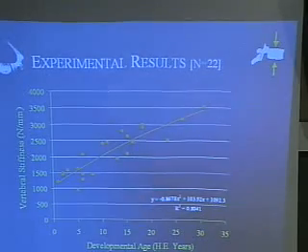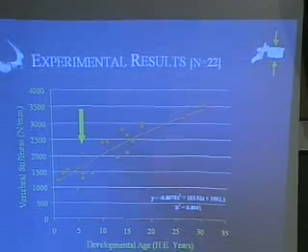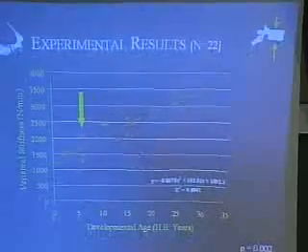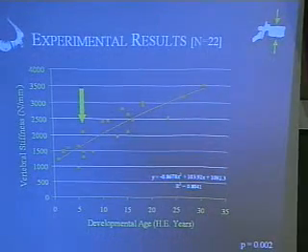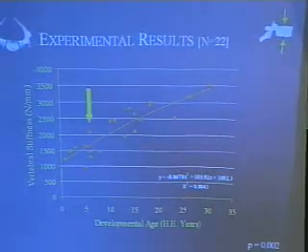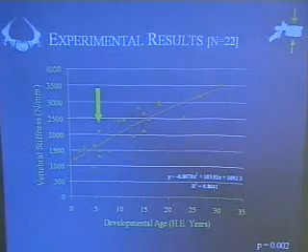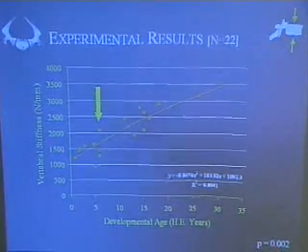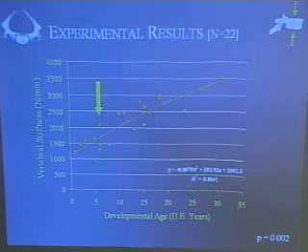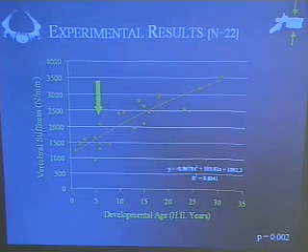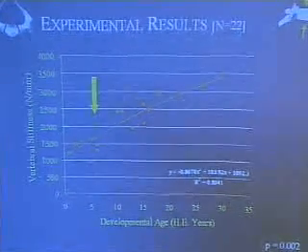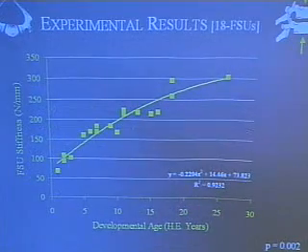Not terribly unexpected. And I point out the 6-year-old age range to show you that there were only a few specimens there, and so our modeling effort actually involves the use of our line through the middle here to try and best approximate those 6-year-old properties instead of using one specimen or two specimens depending on what we might have at that age range.